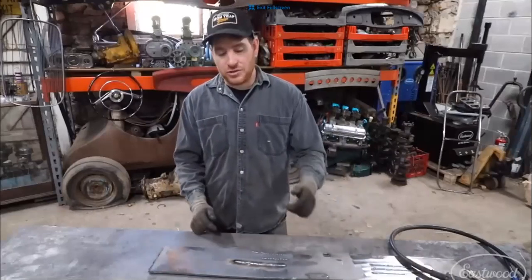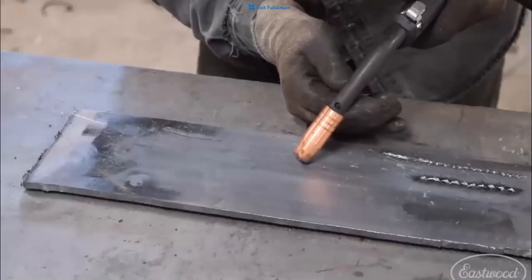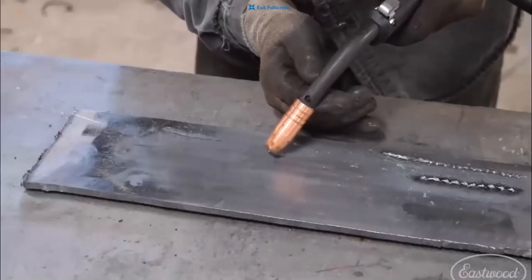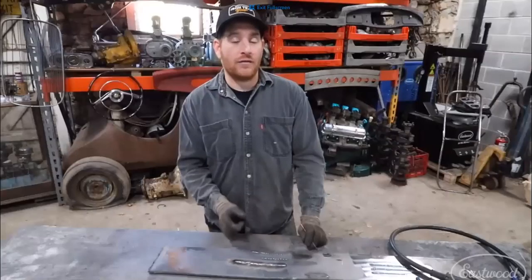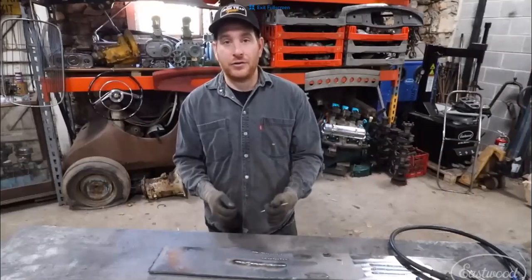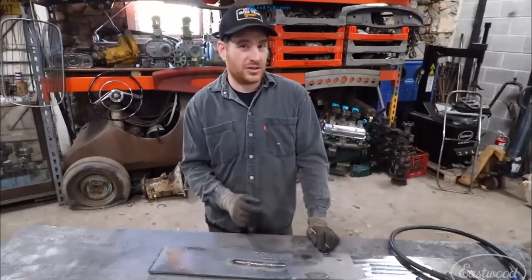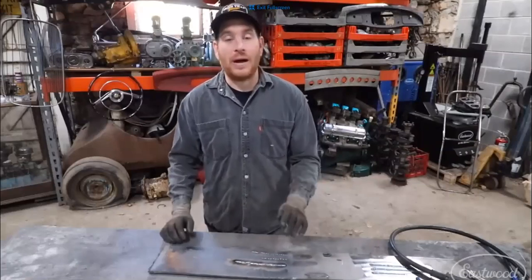The other thing I like to do is try and keep a nice, steady, consistent height off of the panel with the tip of your MIG gun. I usually like to be 3/4 of an inch to an inch total distance off of the panel, and you can adjust from there. That's a good starting point. You don't want to be much more than an inch or a little over, because you might start having that problem where it's going to start spinning or piling up for you.